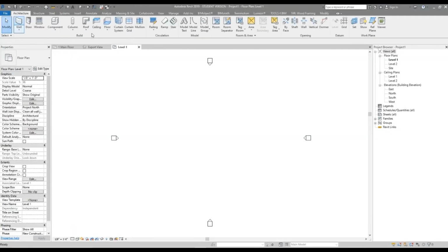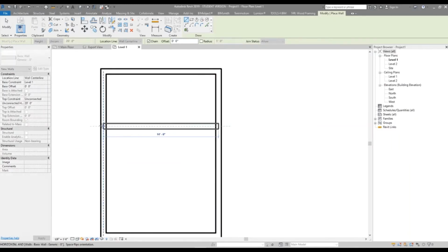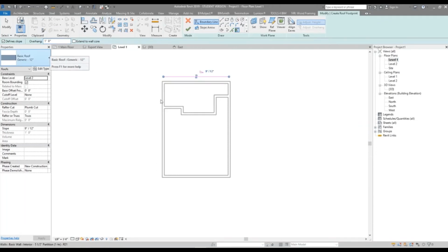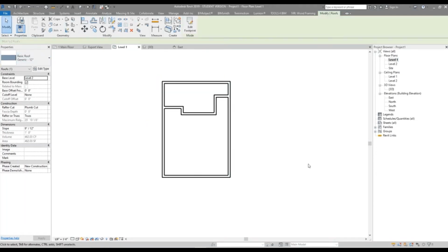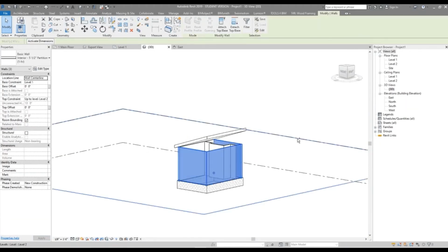To speak specifically about the process of what was done in Revit, the first step was to come up with a basic model. To do this, I used the base tools that Revit offers and modeled in things such as walls, floors, footers, roof, stairs, windows, and doors. The intent of all this was to create a floor plan and a template that the rest of the model would be based on for the entirety of the project.